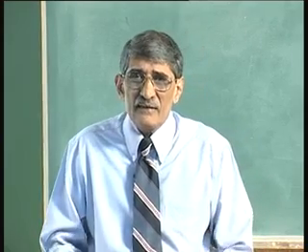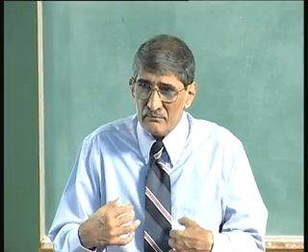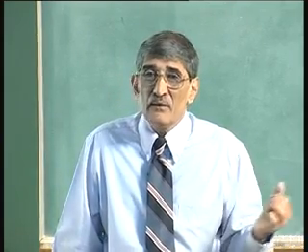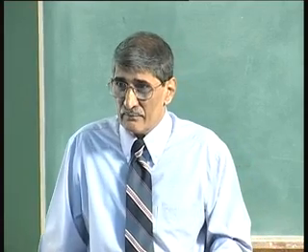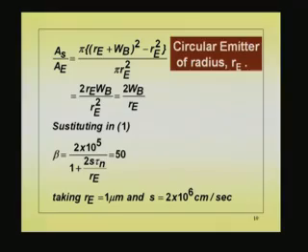It is just like putting a metallic layer, an elemental layer on the surface, that actually increases the recombination current drastically. So, thermal oxide or native oxide of gallium arsenide does not work. So, do not think of putting native oxide on the top of that.